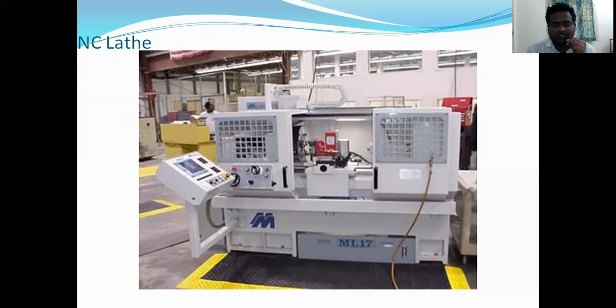The operator's next job is to load that program on the machine. The machine then reads that program, and according to that program, it does the manufacturing process on that product. So here the operator has to do only the loading and unloading. It is a semi-automatic machine. Semi-automatic means that loading and unloading has to be done by the operator. That's why it is called a semi-automatic lathe.